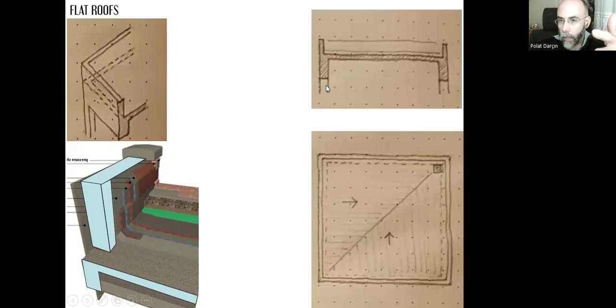That's why our section can be drawn like that. There shouldn't be a line here because we prefer reinforced concrete, the same substance, and we cast them all together. Here, as you can see, the thickness of the floor slab is 10 centimeters. This beam width can be minimum 25 centimeters.